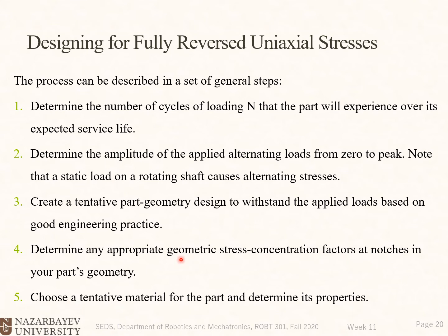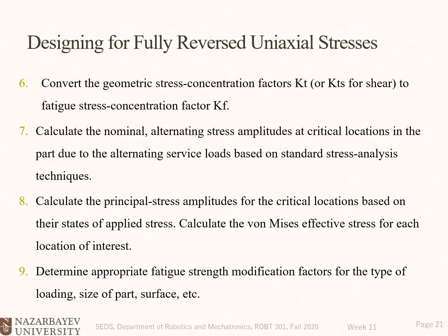So you need to calculate those KT. Fifth, choose a tentative material for the part and determine its properties. You need to choose a material anyway for your design, so choose it and extract those material properties.